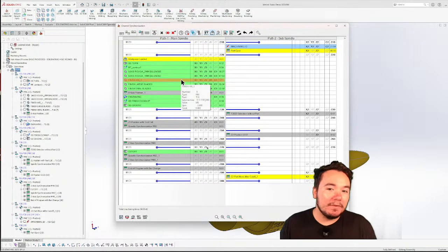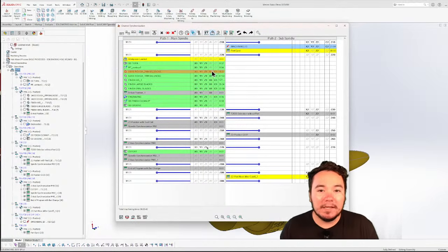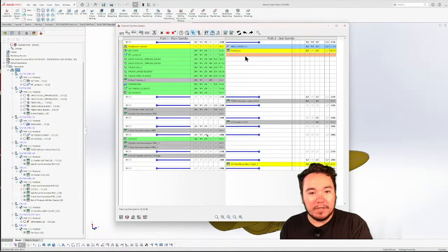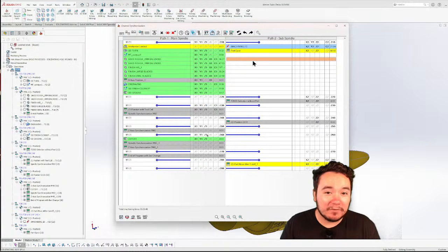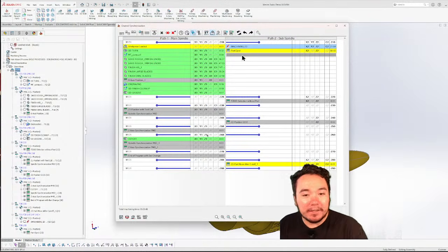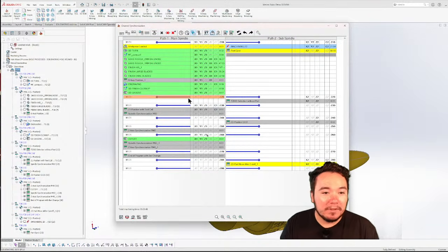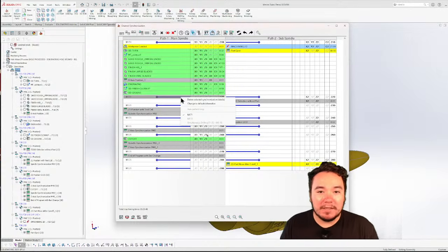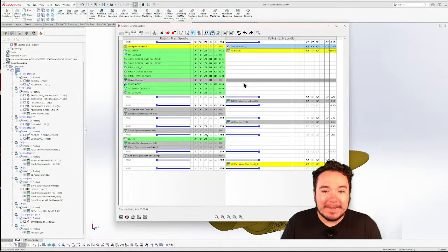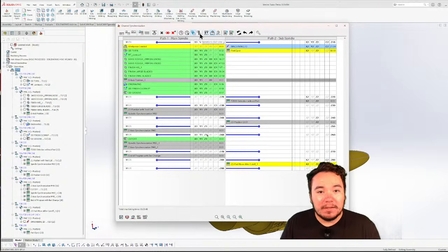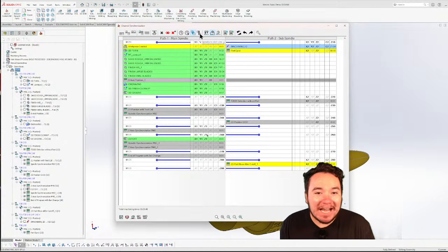So from there it tells the sub that, you know, workpiece is added right at the beginning, and we are ready to start machining. I can go ahead and delete that first wait code. I just selected it and hit delete on my keyboard. You can also, for this one, let's say we needed to get rid of one, I can hit delete selected synchronization labels, and that'll do the same thing. But as you can see, this is our operations clash view. We don't have any clashes.